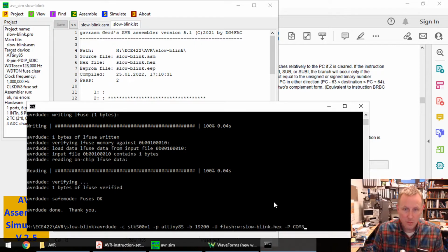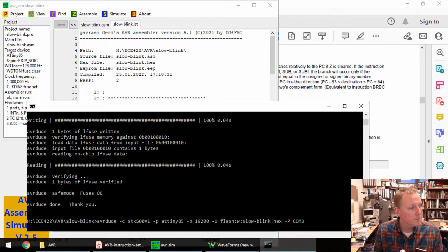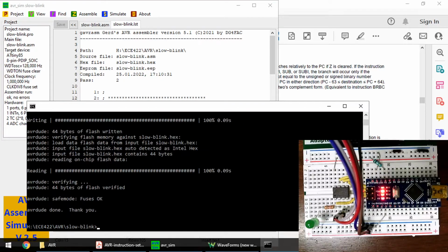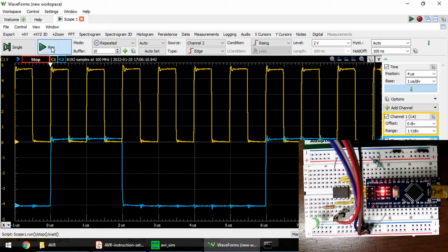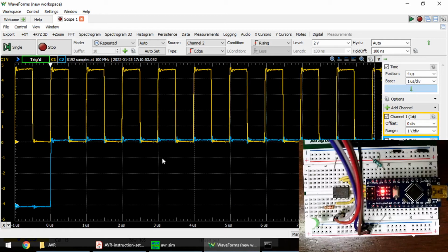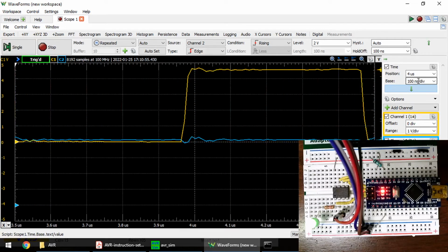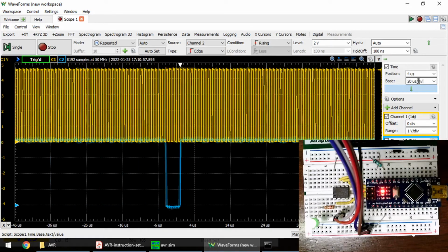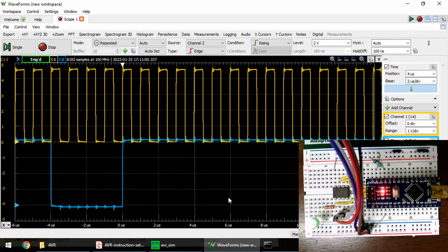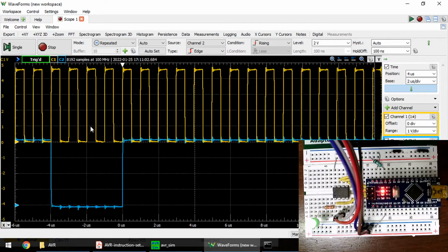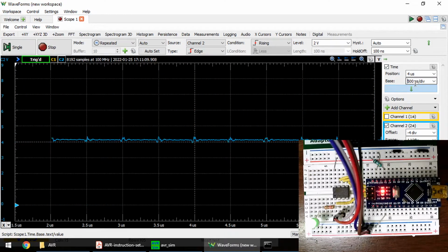We're going to program. The previous command was my fuse. Do that. Watch what happens. Programmed. Here we go. On. Go back to waveforms, run this. Ooh, longer. Zoom out. It goes down for how many clock cycles? 1, 2, 3, 4. We've seen 4 clock cycles.